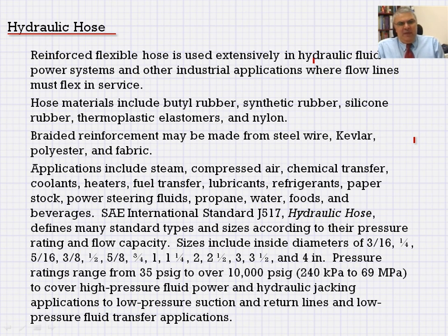pipes. The reinforcement, of course, may be made of steel wire, Kevlar, polyester, and fabric. Remember, if the hose requires flexibility, then one must pay attention to the reinforcement that goes into keeping the strength of the pipe. The applications include steam, compressed air, chemical transfer, coolant.